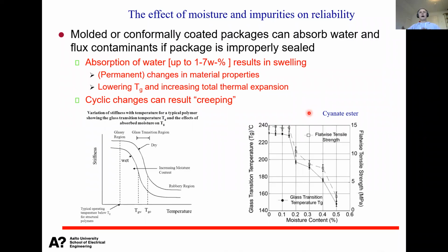So if you want a very high performance, high reliability printed wiring board, motherboard, instead of epoxy based you purchase cyanate ester based, which, if I recall correctly, is one type of epoxy, but cyanate ester has a different type of bond structure. Maybe some of you with a background in polymer chemistry can explain a little better what the difference is there.